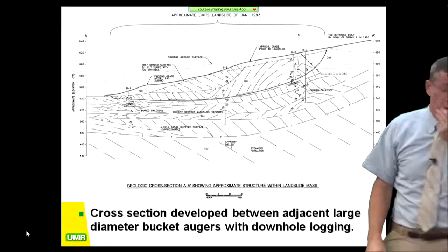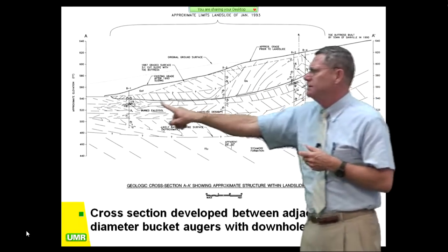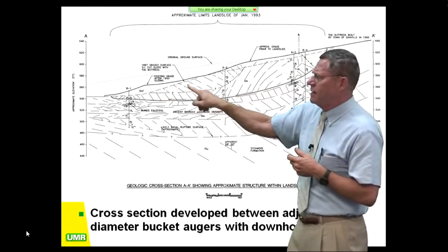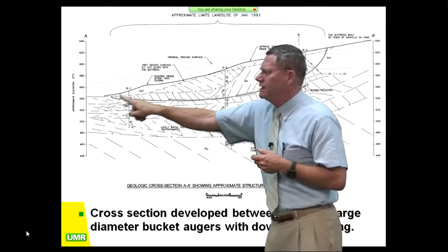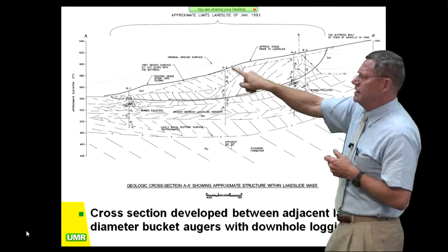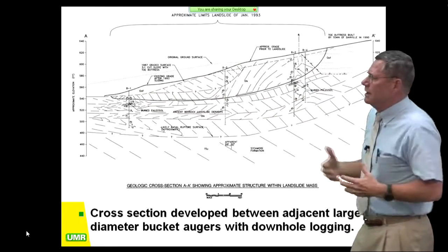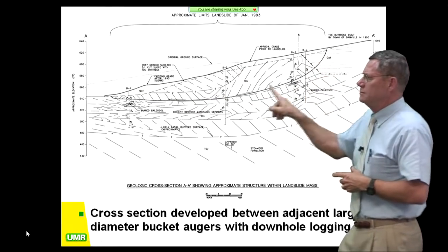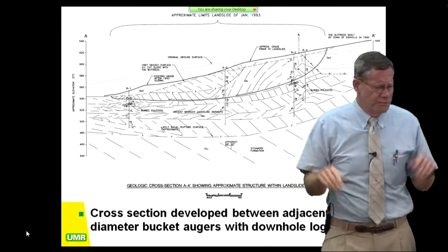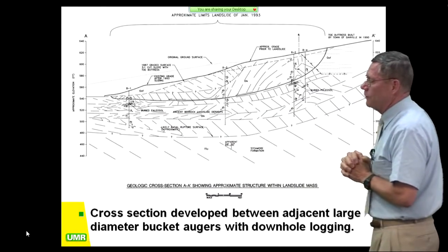Now, here's real world. Bedrock landslide, active slide right here. Previous slide, a lot smaller. This previous slide had been repaired with a buttress fill right down here. The original hillside, which had been graded less than 10 years previous, was right there. And after they had done this repair, a couple years later, lots and lots of moisture, and this thing comes out and mows down about 8 houses, all of which are around $750,000 value houses at the time. This is about 1994, 95.